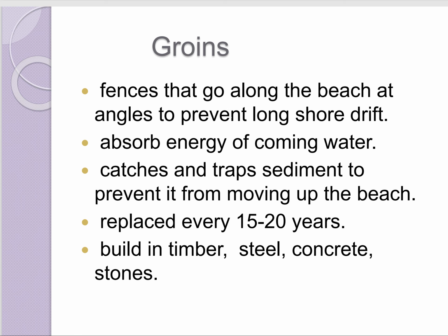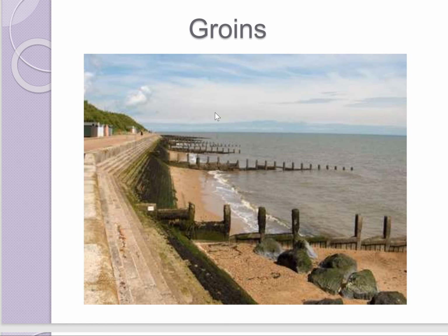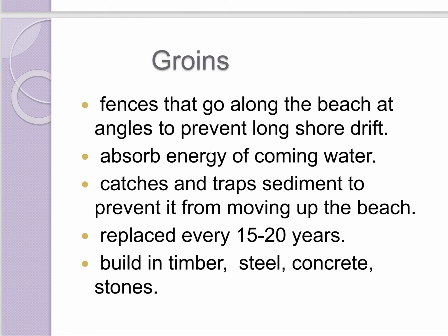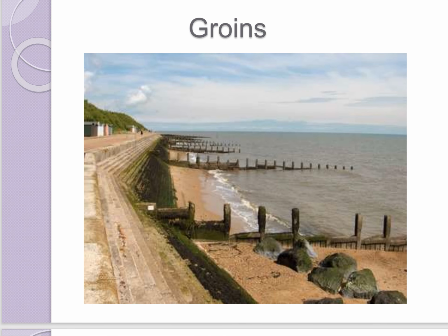The next type of structures is called groins. These are fences that go along the beach at angles to prevent the longshore drift. So you can see groins in this picture, which are provided at different angles towards the sea. Groins absorb energy of incoming water, catch and trap sediment to prevent it from moving up the beach, and are replaced every 15 to 20 years. They are built in timber, steel, concrete and stones. So groins are fences made of either timber, stone, concrete or steel.